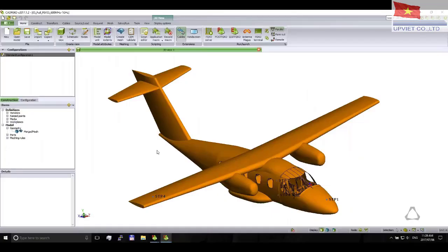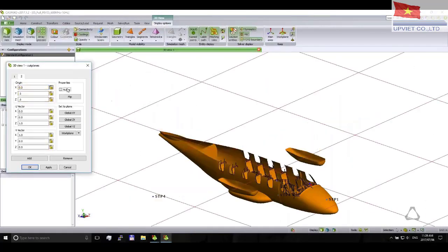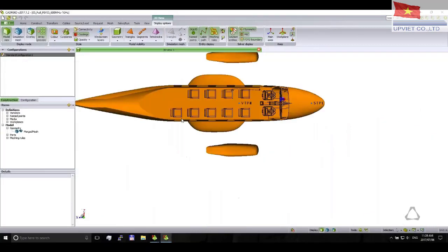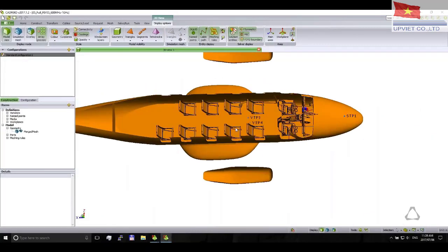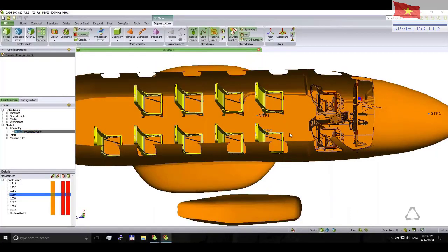So switching now to FEKO, here you can see the simulation model. Firstly, the model has quite nice detail, which we can see inside the fuselage. For example, we have some information about the different seating configurations, also in the cockpit, as well as some control panels, and finally also the cable harness geometry. And here you can see the port where we calculate the induced current. This model is from the highest frequency band.